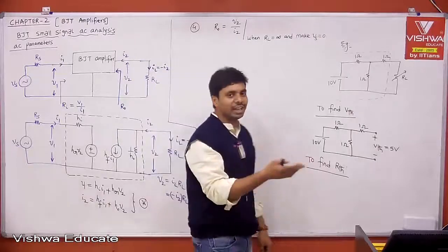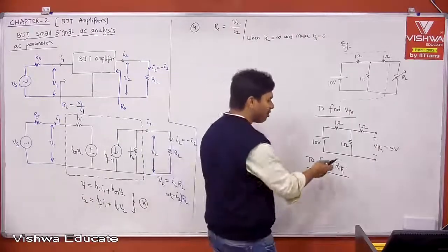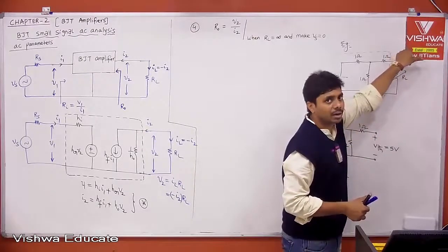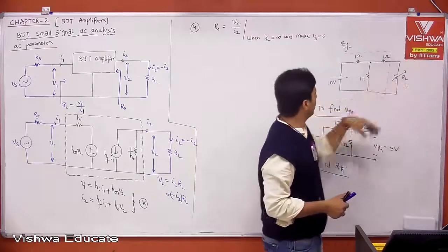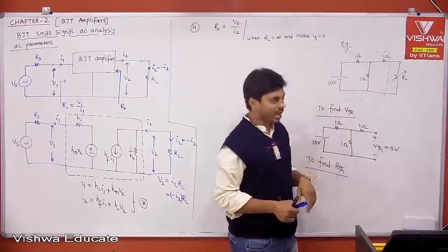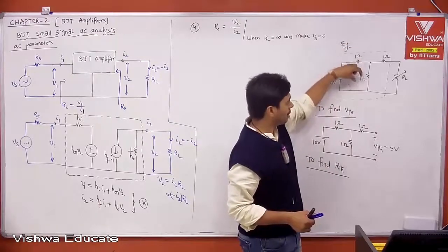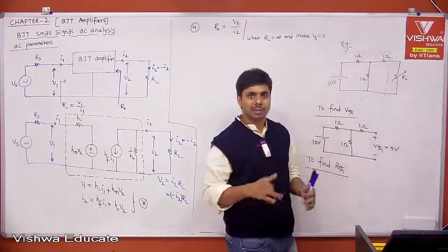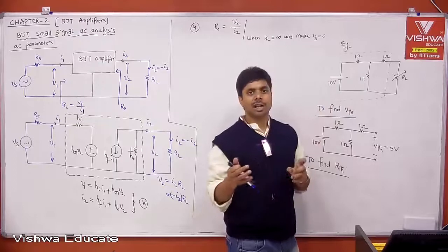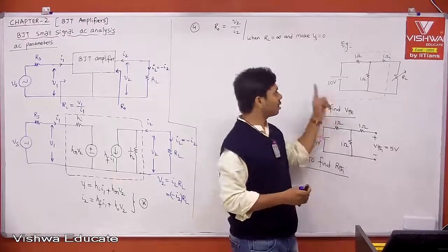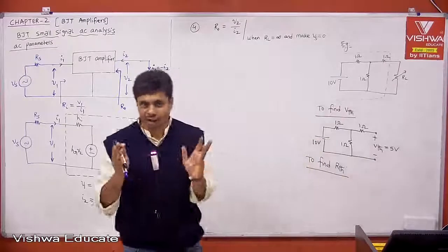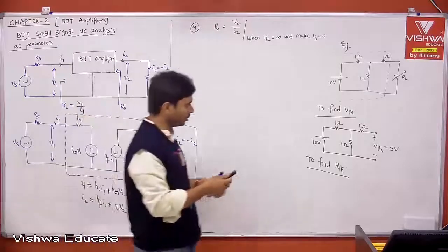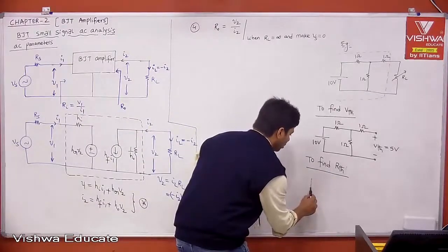But tell me, knowingly or unknowingly, how are we calculating RThevenin? We are excluding the load. We are not applying the voltage and we are not getting the current. Remember, the methodology says that if there is a voltage source, short it. Then 1 parallel 1 is 0.5, in series with 1 is 1.5, that is RThevenin. My question is, the methodology says short the voltage source, and if there is a current source, open it, right? Then why are you shorting the voltage source while finding RThevenin? If you understand that part, this is also the same way. To find RThevenin, we are shorting the voltage source.